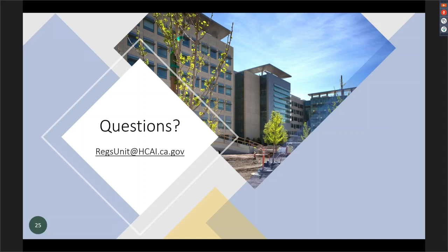So I would say be very careful on what you call an NMA, be very honest about it. And yes, you can proceed with work. You don't have to wait for concurrence. Just make that clear. You don't have to wait for concurrence for work to proceed on an NMA. Now, if something is built by an NMA and it's concurred with, like you said, 3 weeks later, and they've closed up, there may be a chance you have to reopen that to show it was built or convert. So there's a risk. If you're not sure, ask the question before you do it.